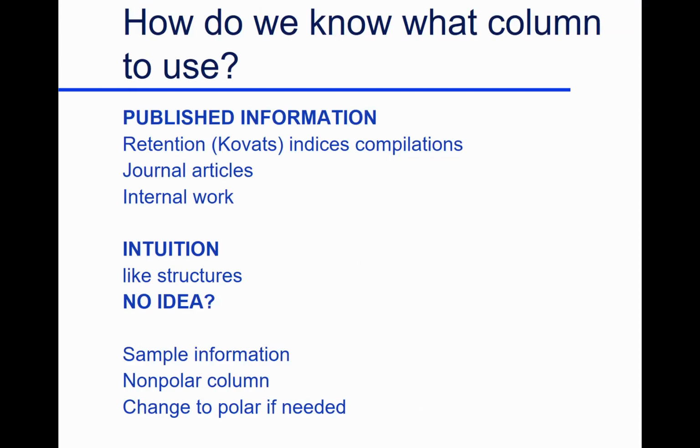Question is, how to make a choice, right? Well, we have a dozen different types of columns to pick from. And so the question always is, what should we use? What should we start with? And the first thing is go ahead and look at published work. That's the simplest. There are very few things in life that haven't been studied by someone somewhere.